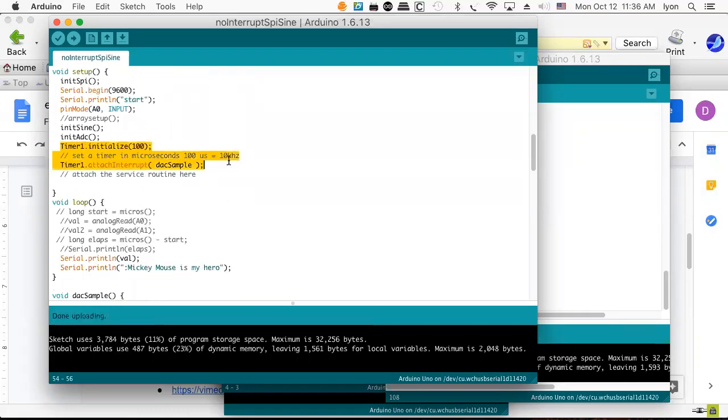So the key, we did a timer attachment. We're doing sampling. If we wanted to sample at 125 microseconds, which is the same sample rate as the A to D converter, we could do that simply by typing it in there. And not to put too fine a point on it, but if I took 125 times 10 to the minus 6, and then raise that to the minus 1 power, I get a number that's 8 kilohertz. So 125. It's not quite the same as what I expected.